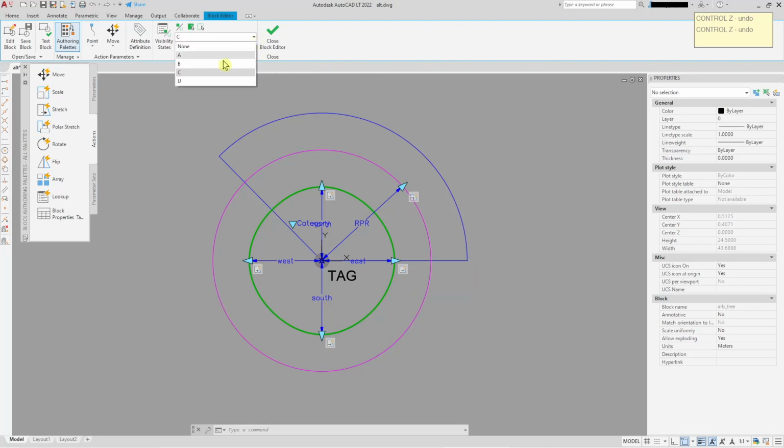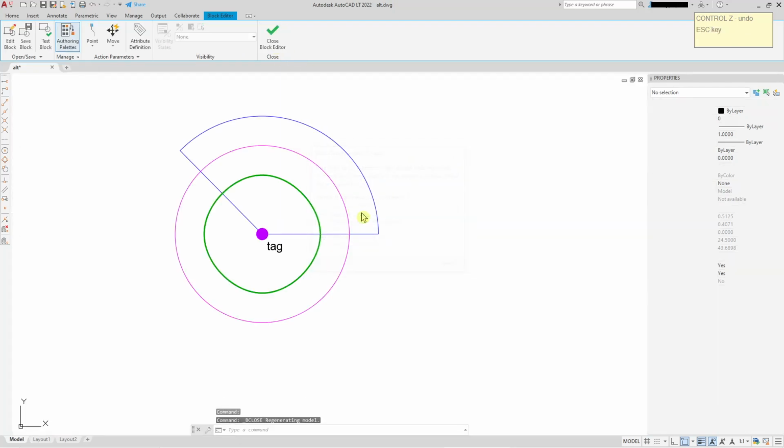And for U, you can decide whether or not you want to show it. If U is a tree to be removed, you wouldn't normally want to show the shadow. So I think I'll leave that as it is, so it's hidden. But if you want to show it, then simply click it, but I won't. So I'll close that and save the changes.